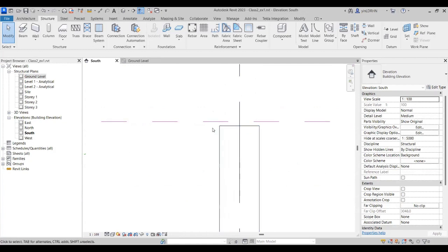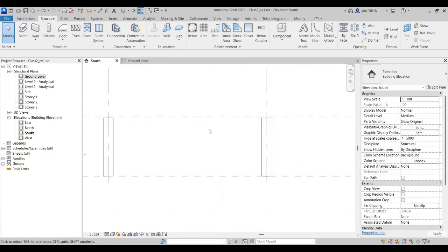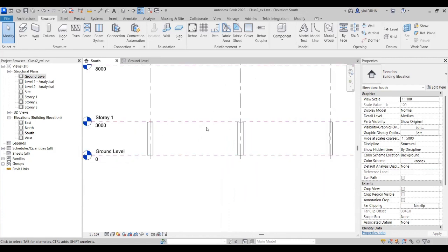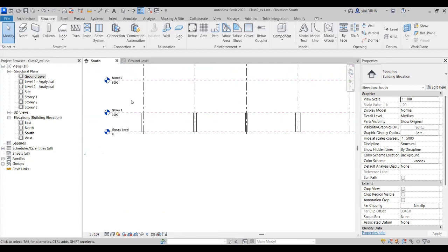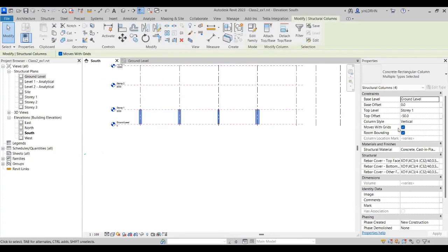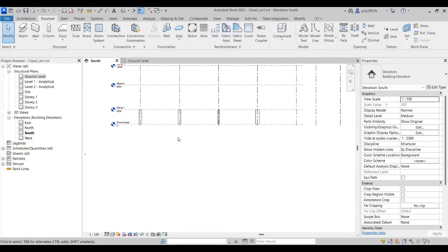Then all your beams are supposed to be drawn here. If you draw them here, then it's wrong. Okay, it depends, right? You can keep it anything, but it should be consistent. Understand? So you have to keep one consistent thing. For easy purpose at this moment, I don't want to complicate too much, but you have to keep in mind this is the way we have to work. For easy purpose at this moment, I make the level a 0. Okay, now I convert this model as an analytical model and show you how it looks.